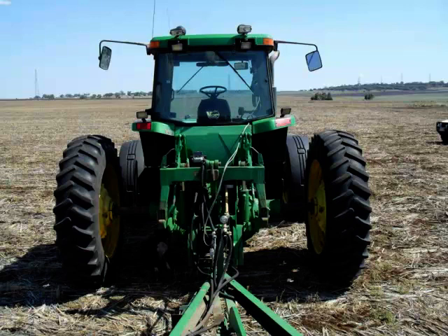You can see on here there's the cast inner. Don't use the pressed inners. They're not as strong. So if you've got duals, just flick the dual off and then just use that inner. The inner duals are always typically the cast inners, a bit stronger. So the back end's fine.